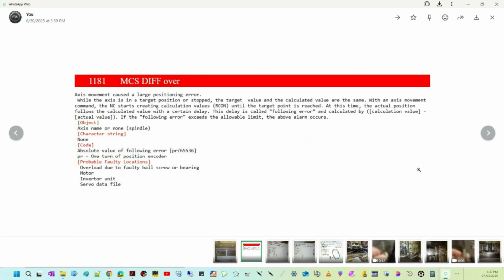Okay. And when that gap, that following error, gets too big, bigger than the allowed limit, bang, the machine throws this alarm. It's a safety mechanism, really. And that string at the end, FFFCEFD, that's like a snapshot of diagnostic data taken right at the moment the alarm happened. Super useful for the techs.